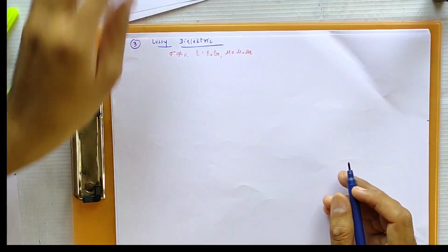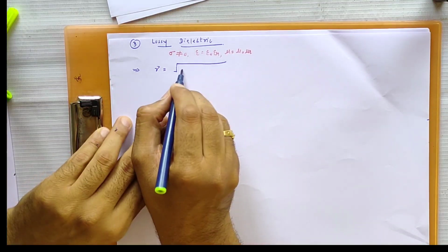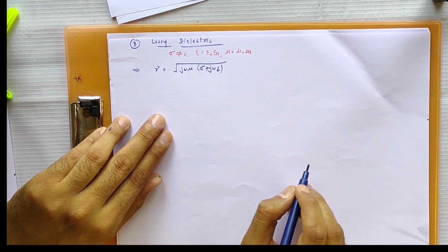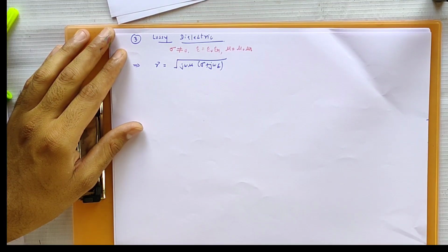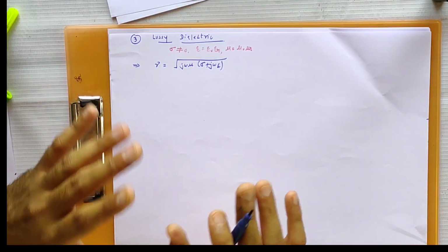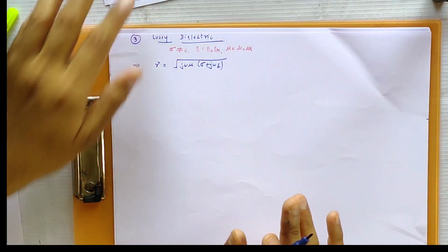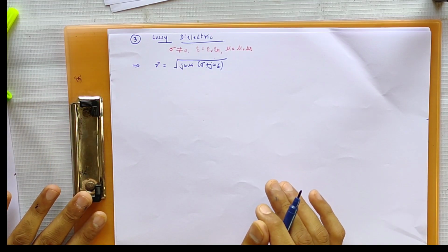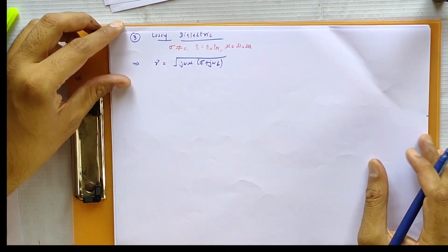We do all those things, but now the problem is, see here, the propagation constant is the square root of j omega mu times (sigma plus j omega epsilon). If you notice, sigma is not 0. So we apply the Taylor series expansion method to solve this equation, and finally compare the real part and the imaginary part. The equation becomes very large, and it is time consuming.